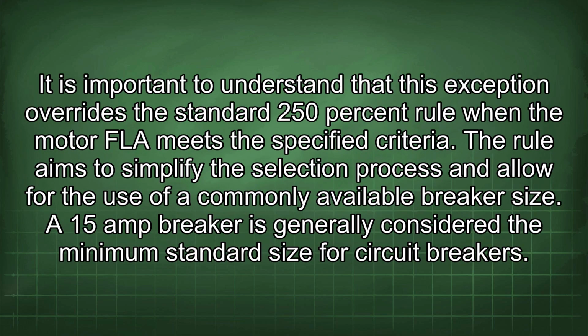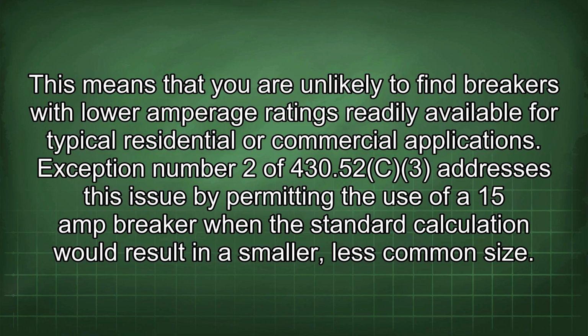It is important to understand that this exception overrides the standard 250% rule when the motor FLA meets the specified criteria. The rule aims to simplify the selection process and allow for the use of a commonly available breaker size. A 15 amp breaker is generally considered the minimum standard size for circuit breakers. This means that you are unlikely to find breakers with lower amperage ratings readily available for typical residential or commercial applications.